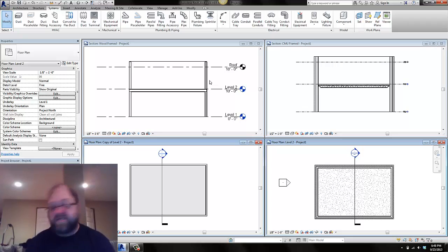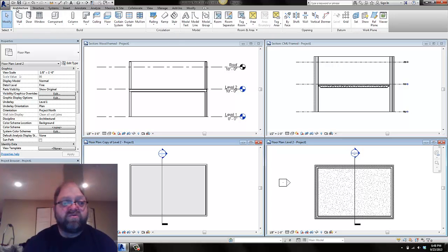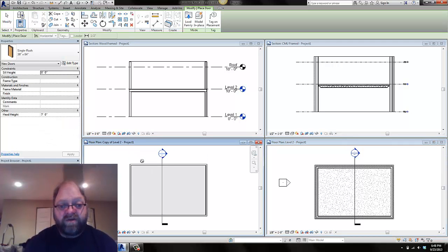So why do you care whether it's a domain-specific modeler or not? Well, the reason Revit does it is because when we have these domain-specific tools, we can create rules about how the tools interact with one another. I've talked about that before, and we've seen that behavior. If we have a wall here, and we have a door, when I place the door, it won't place until I get near a wall, and then once I put it into the wall, it will go in.